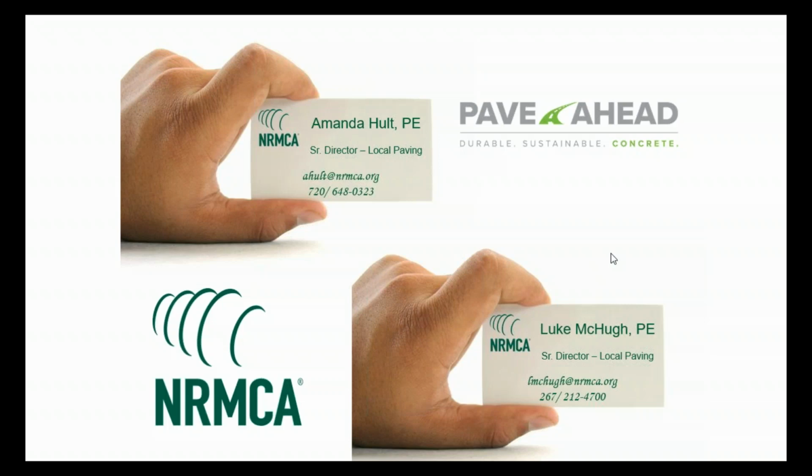Okay, the next question is jointing required in roller compacted concretes. Many times, no. When roller compacted is done, a lot of times in the locations where they are placing roller compacted concrete, they're worried more so on the durability of the pavement, and so aesthetics are not something that they're really worried about, and so a lot of times they will leave them to crack naturally. It's a drier mix, but it is a concrete pavement, so it's going to crack.